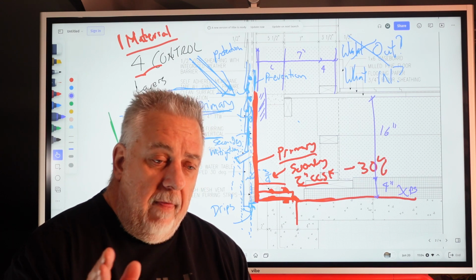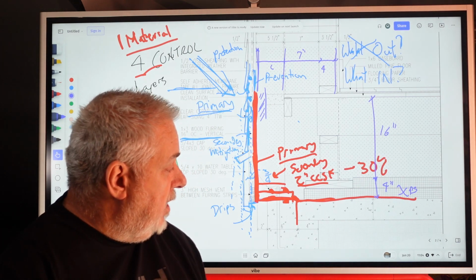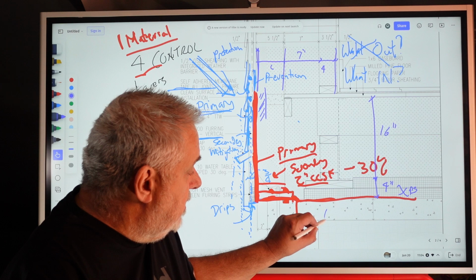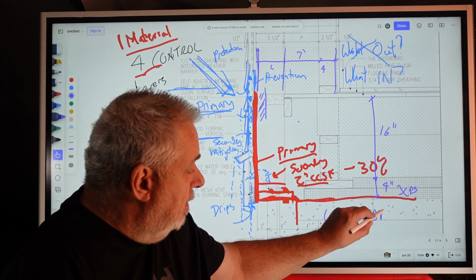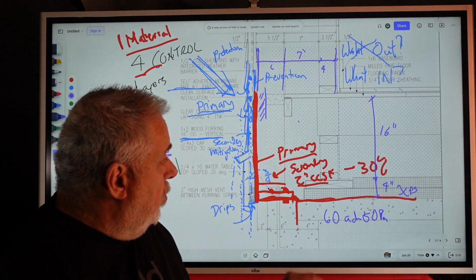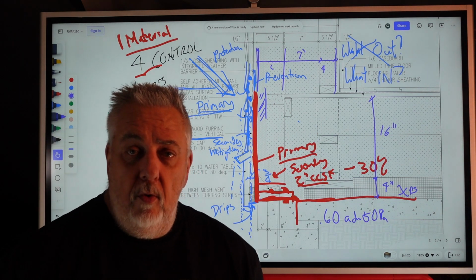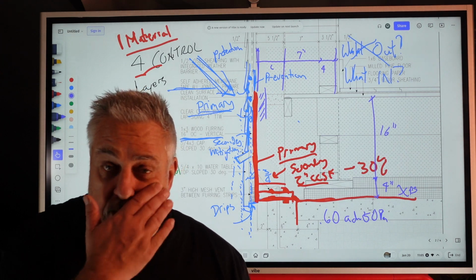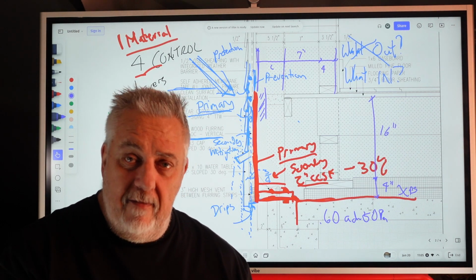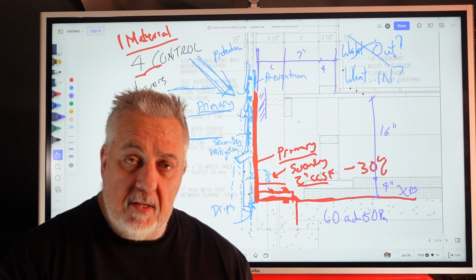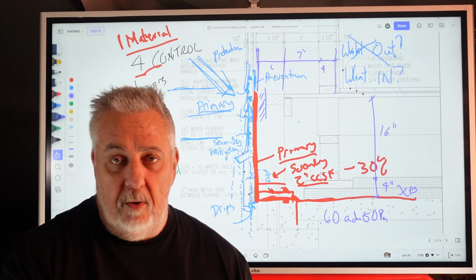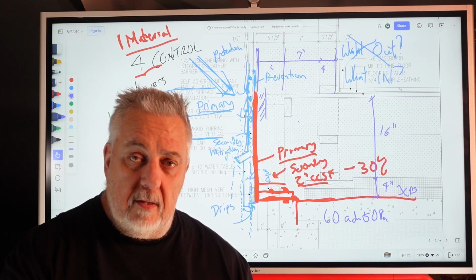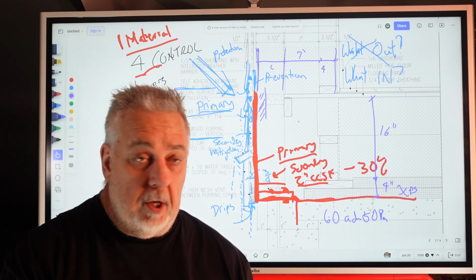That, coupled with an air tightness of 0.60 ACH50, means that we're really not pushing anything through the wall via air leakage. Now it's very important, because moisture that moves via air leakage is an order of magnitude over moisture that moves via diffusion, right?